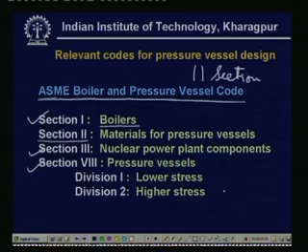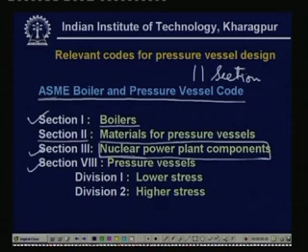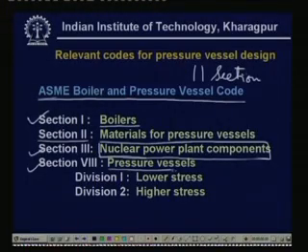Here we will have to consider many other things, such as the vibration problem and fatigue, that is variable loading problem, etc. All of them are very important, because we want a very reliable design. Whenever we have nuclear power plant components, we cannot compromise with anything, so we have to check for other things rather than static loading in order to make the design safe. Now, section 8 deals with the pressure vessels.